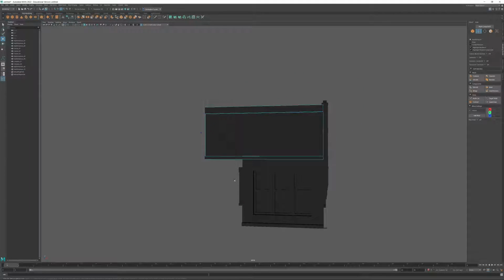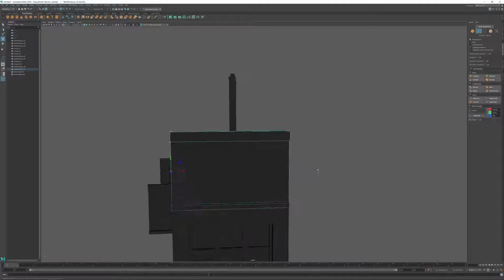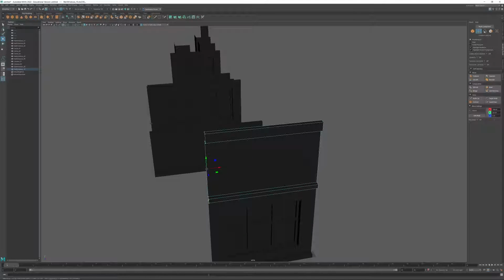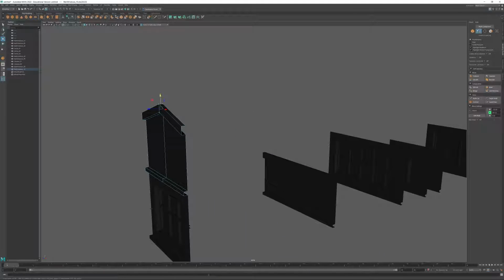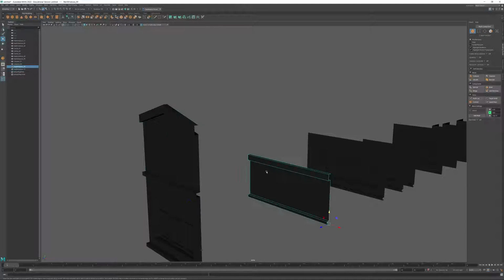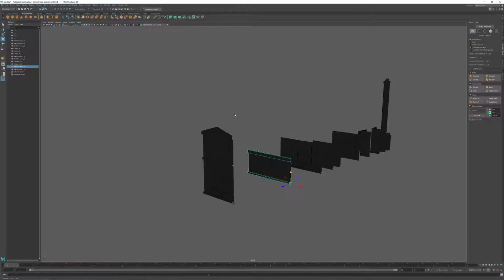We know that these vertices have to be at -300 to make this the right width. And this piece actually has a peak. So if I grab this and connect, I can hit enter. I can grab these vertices, turn off my snaps, and move them up until that peak is correct. And again, this will now fit along with that piece.